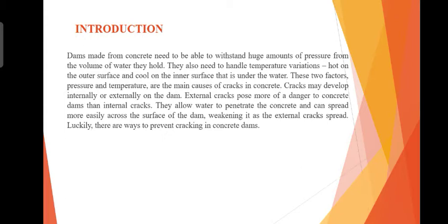Dams are made of concrete. You also know structures are generally made of concrete and RCC. Dams need to withstand a huge amount of pressure, meaning the pressure exerted by water on the body of the dam. They also need to handle temperature variation, like seasonal variation in summer, winter, and monsoon, so due to that also cracks occur. The two main factors, pressure and temperature, are the main causes of cracks in concrete.